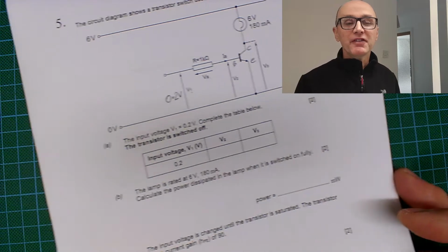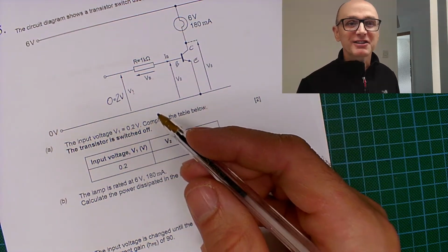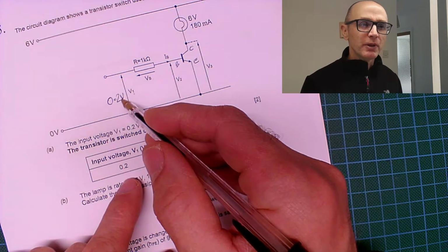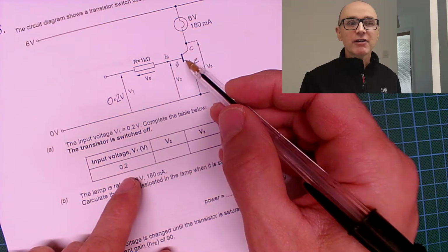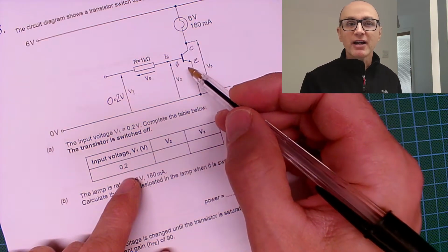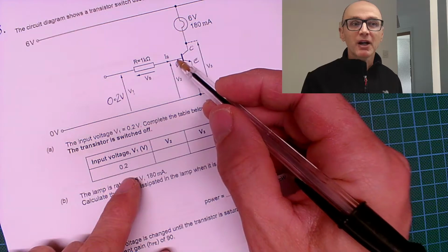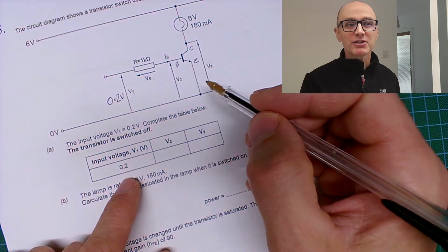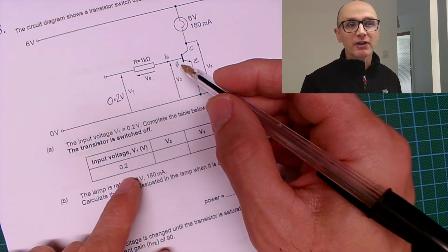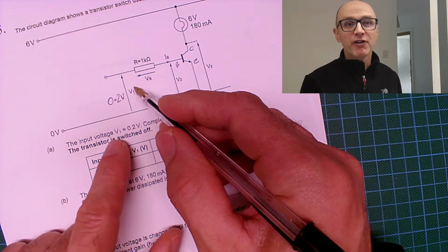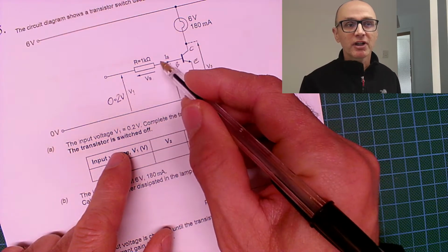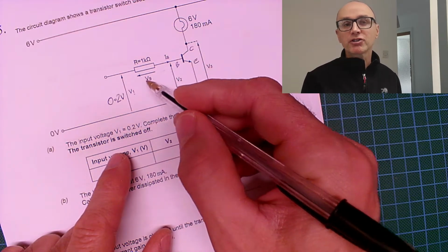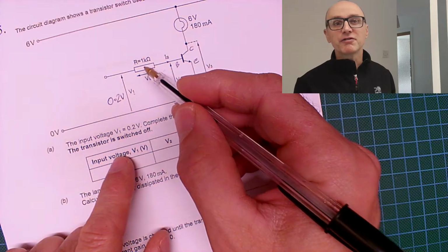Now, there's a lot of stuff there, but hopefully that's going to arm you to be able to answer some of these questions. So if we've got 0.2 volts, we know we haven't reached that 0.7 volts bias point to get a significant amount of current flowing across the base emitter junction. And do remember as well that not only could that input voltage be dropped across that junction, but also once current's flowing, there's going to be some voltage drop across here, because if you've got a resistance and you've got current, then you've also got a voltage drop.